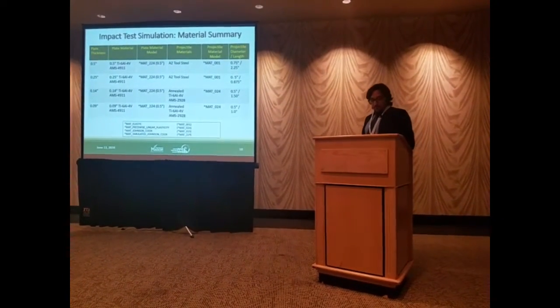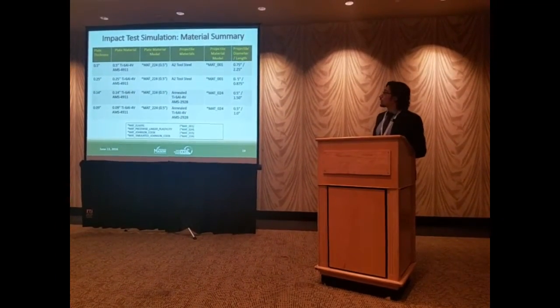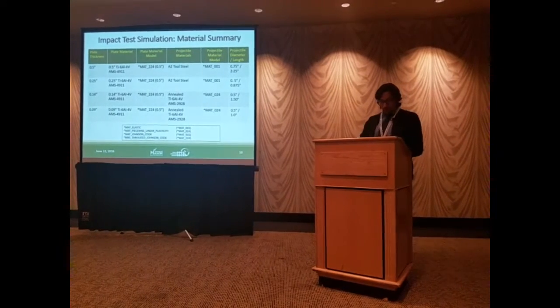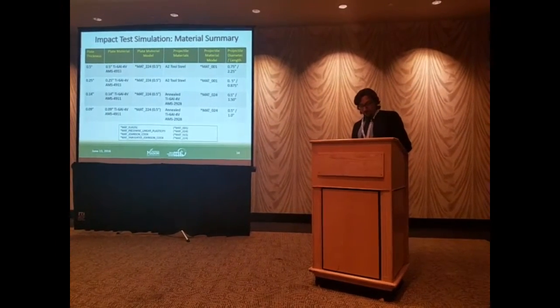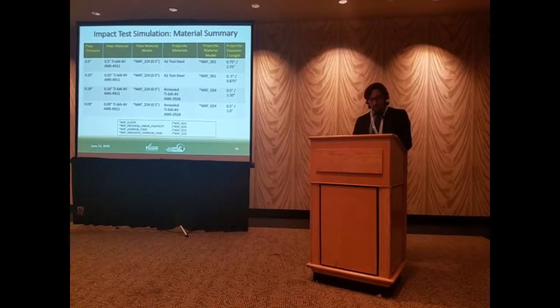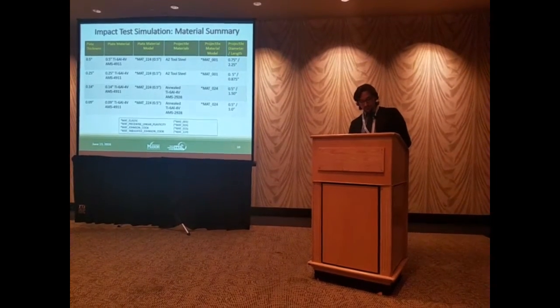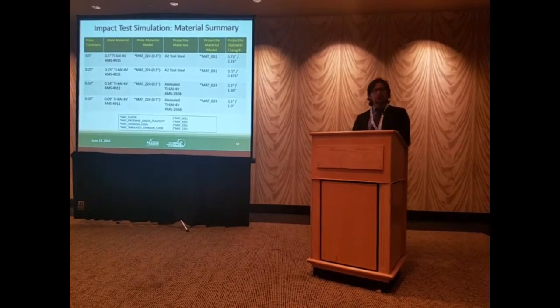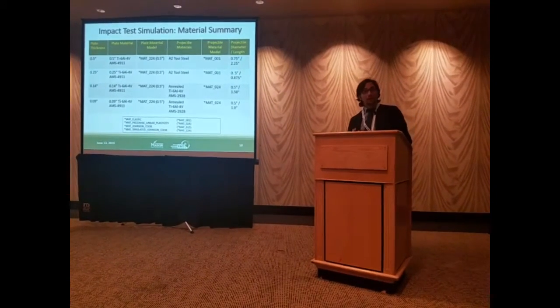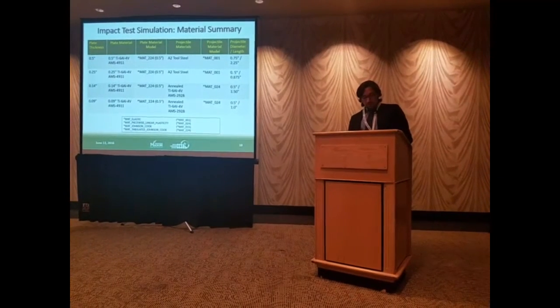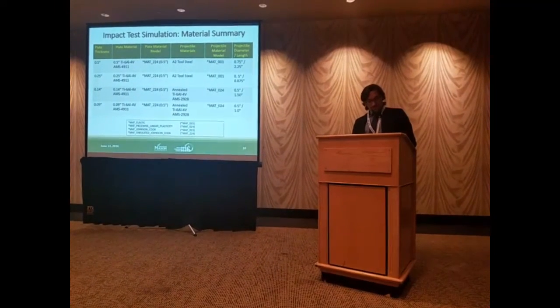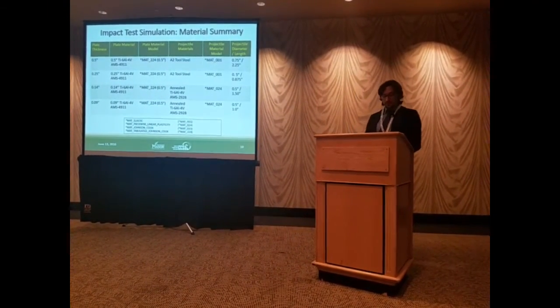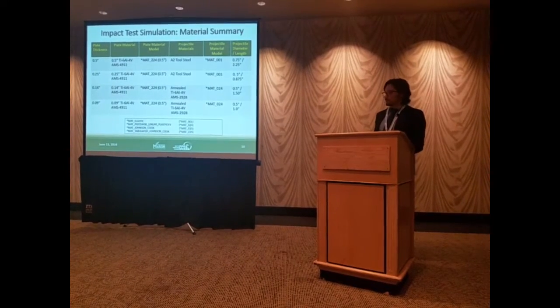Here is the simulation material summary for the half-inch and quarter-inch plate. The projectile used is made of A2 tool steel, so we use MAT elastic to describe its behavior, because A2 tool steel is a hard material, and the plastic deformation after the impact is negligible.